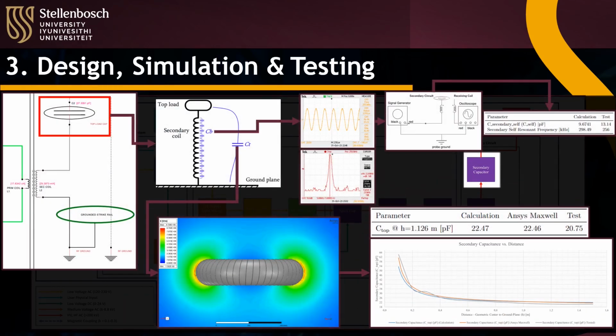The decision had also been made to implement the secondary capacitor utilizing a toroidal top load. This toroidal top load was simulated in ANSYS Maxwell, indicating high E fields on the wires of the constructed toroid, which will show where the discharges will protrude from.